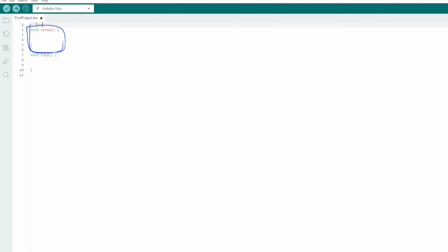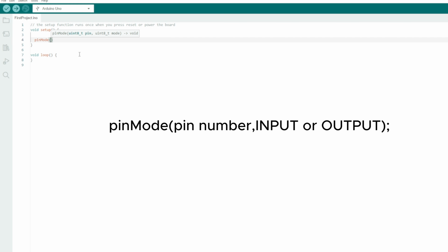The first thing one notices in the code is the void setup function. Inside this function, things will happen that are only done at the beginning of the code and will never happen again. In contrast, in the void loop function, everything inside is repeated over and over again. The first thing the Arduino needs to know is how the pin the LED is on will behave. This is done by the pinMode function, in which we need to know the pin number. And how the pin will behave.